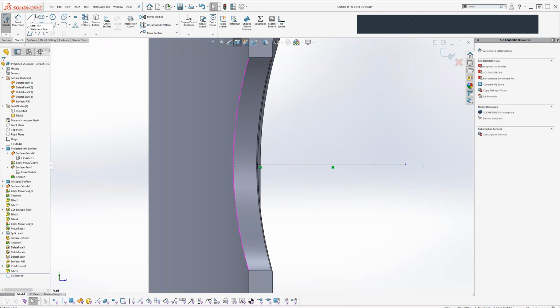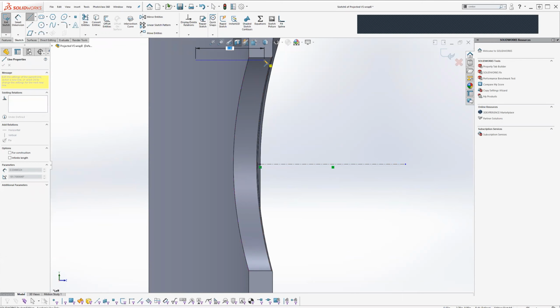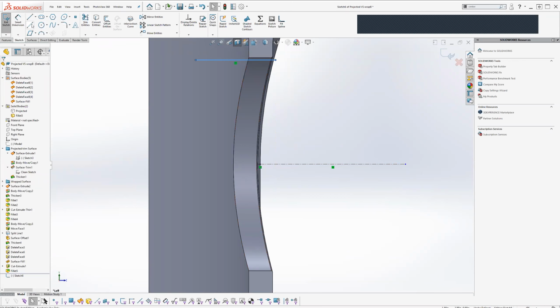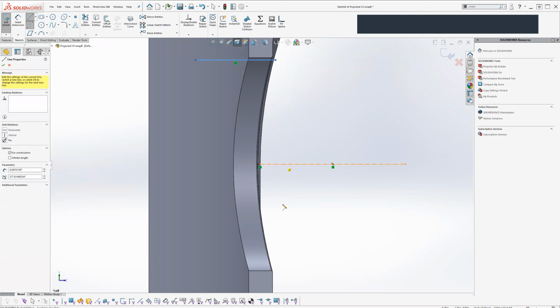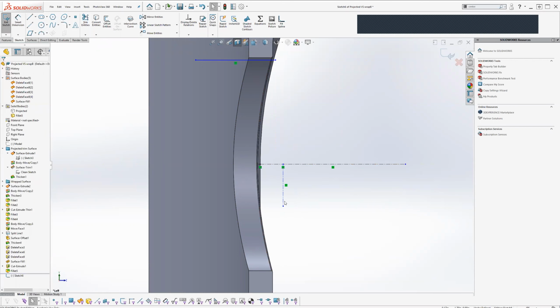So the rest is just going to be a simple revolution. You decide what the tolerance of that's going to be. And let's say I want it to be slightly raised at the apex. And then from there, let's say this is going to be the top of the knob.